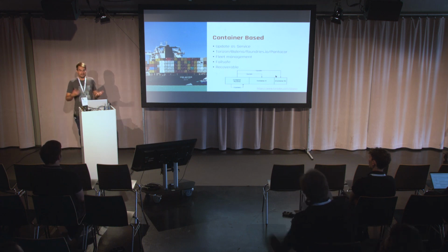I would say this is kind of update as a service, because what all these providers of such functionality, like Toradex with Torizon, Balena with Balena, Foundries.io with their solution, and Pantacor do, they provide you a host system which they take care of, how they update it, they make it fail-safe, and then you can just package your application into a container and ship this container to the embedded device. And they take care that these things happen fail-safe. You don't have to really worry about it.